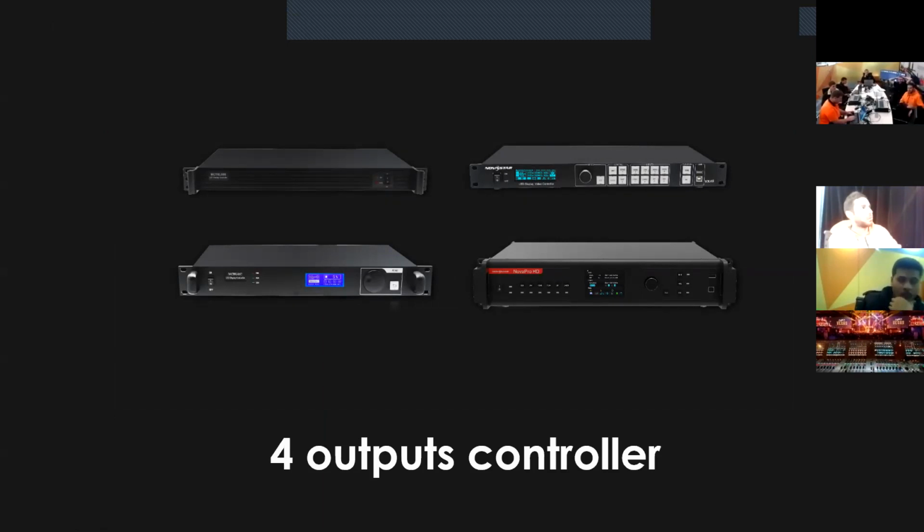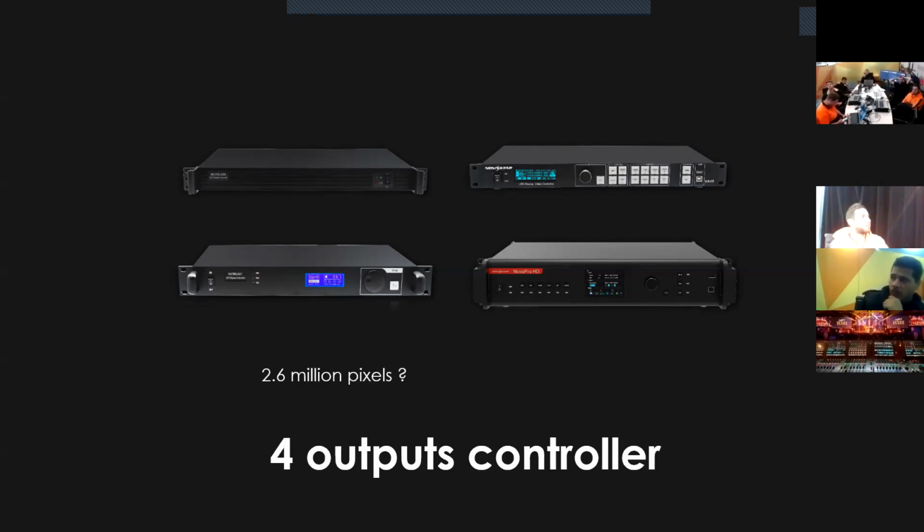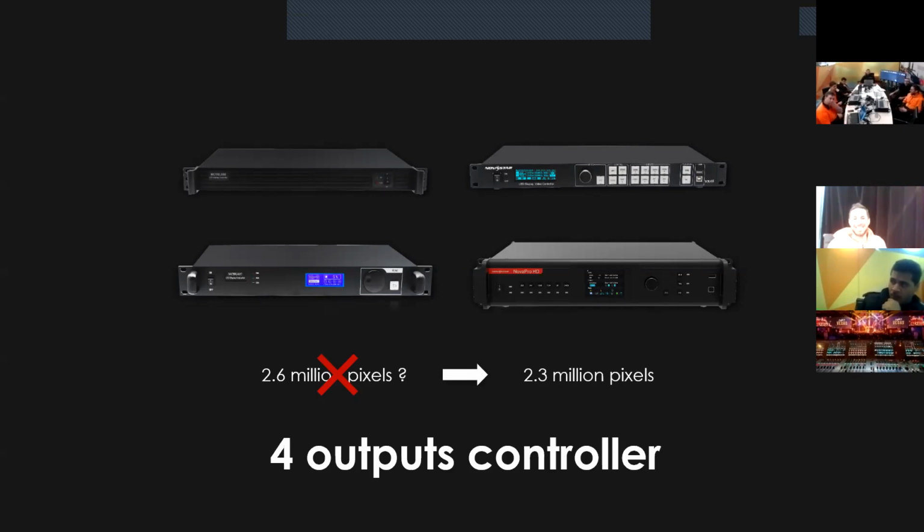Let's say one port got the capacity 0.65 million pixels, and the MSD300 got 2 ports, so it equals 1.3 million pixels. But what about this one? If that equals 2.6 million pixels? The answer is no, it's not 2.6 million pixels. This is 2.3 million pixels.